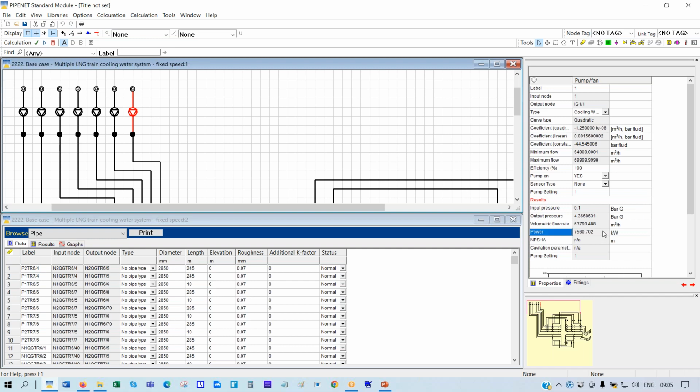So it's quite a big saving in the power consumption, even though the speed is only changing slightly because the flow rate is so high. And cooling water pumps normally have a low delta P, and that's why you can use fiberglass pipes, because the discharge pressure is not very high. So if you trim the flow rate, you can change a huge amount of power, and you can see that here.